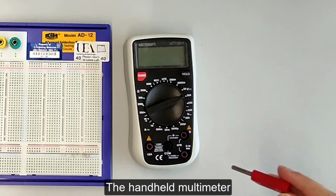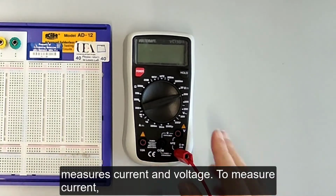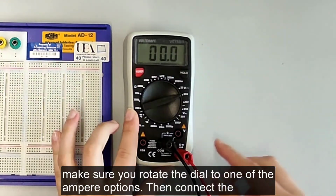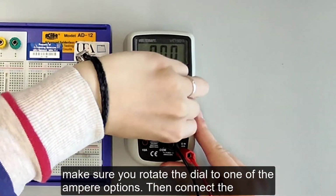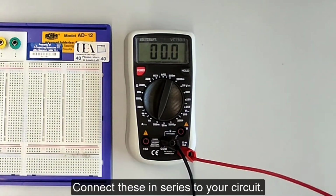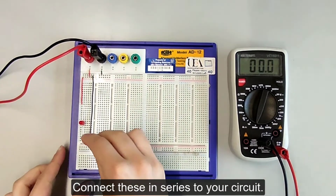The handheld multimeter measures current and voltage. To measure current, make sure you rotate the dial to one of the ampere options. Then connect the red wire to input A and the black wire to the COM input. Connect these in series to your circuit.